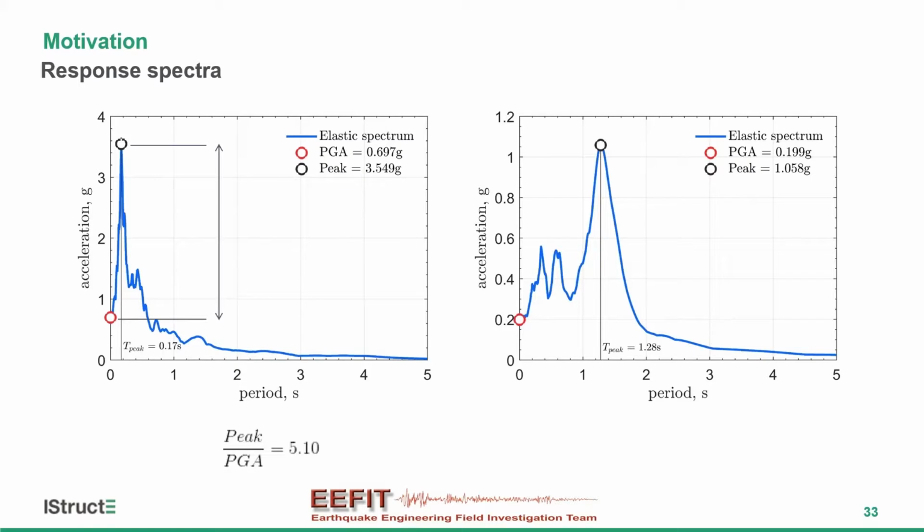And here you can see the same. So basically, an accelerograph is capable of measuring what's happening here at the peak ground level, and we are interested in what's happening up here. We need to be able to record this amplification in the signal. So this is one response spectrum from an earthquake from Chile, the 8.8, the almighty 8.8, 2010, and this is from Puebla in Mexico in 2017.